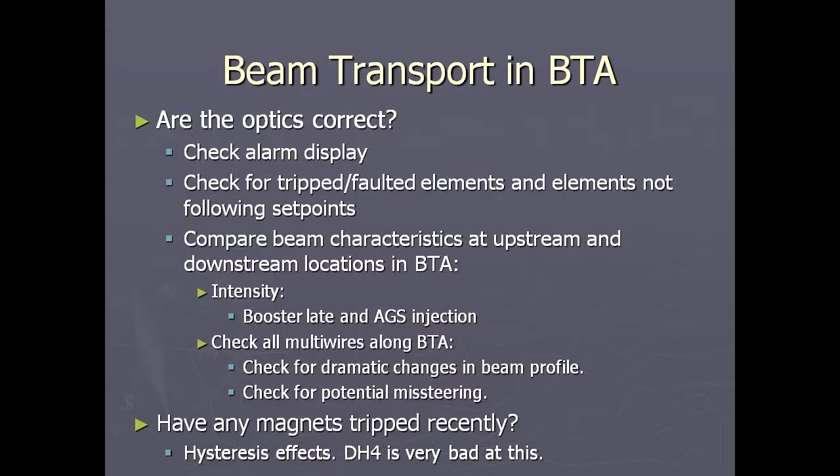Right. Where is our current MUX system? Anything faster than a millisecond, we can't get in the MUX. So if it's faster than a millisecond when it pulses, it's going to have to be a hardwired signal, otherwise it'll be just distorted. So any kicker, PUEs, wall current monitors are all going to be hardwired. And the bumps and the stuff, you can all get from crossbar. Right, I just listed the places in the directory.